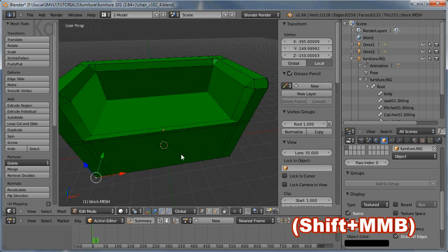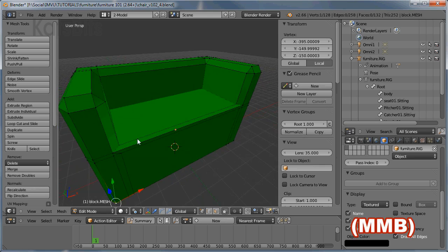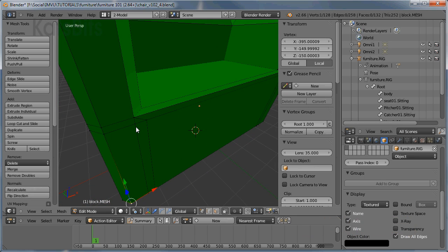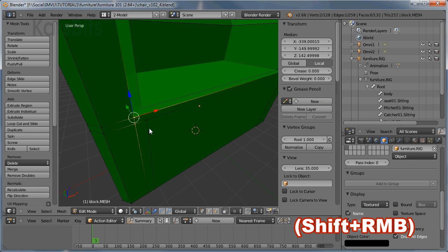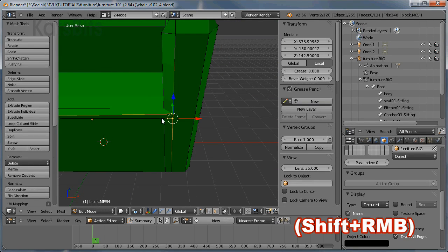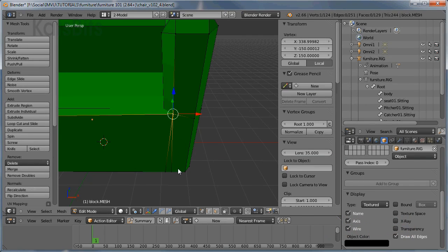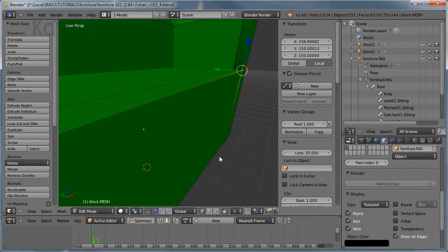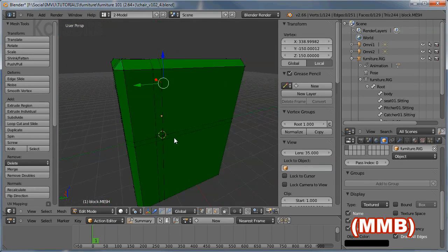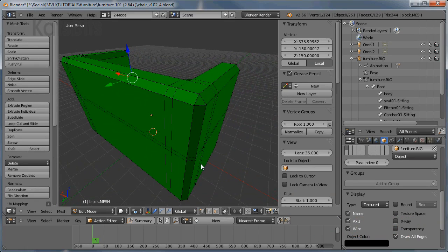Now the reason for leaving that leading edge alone was to just make sure that we collapse the correct edge on both sides before we then collapse it. So selecting that bottom vertex first, the leading edge corner and this vertex, collapse them all together, same again on the other side, and that creates a slight bevel on the front edge of the seat. So it's now a question of going around the rest of the mesh to remove the remaining vertices.